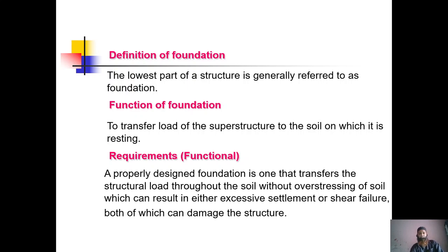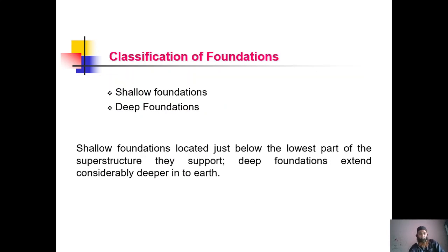Requirements: a properly designed foundation is one that transfers the structural load throughout the soil without overstressing the soil, which can result in either excessive settlement or shear failure, both of which can damage the structure. If the foundation is not designed properly, there are chances of settlement of the whole structure, or sometimes base shear failure takes place. The base moves away because of the friction and the lateral forces coming onto the structure and the soil. So it is very important that the foundation be designed very properly.